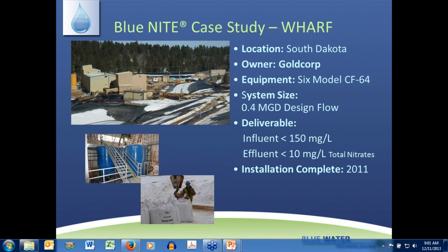If you're trying to remove transition elements like zinc and you have to actually raise the pH, we're looking at caustic, mag hydroxide, lime, soda ash, etc. Those are pretty commodity and inexpensive chemicals. And then if we need a polymer chemistry, there's a lot of polymer chemistries that work very well that are very inexpensive, upstream in a clarification stage before we get to adsorption.